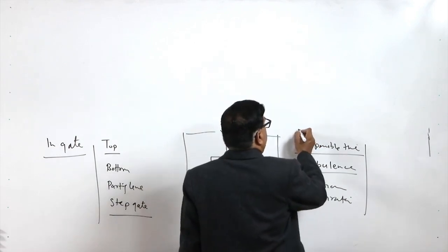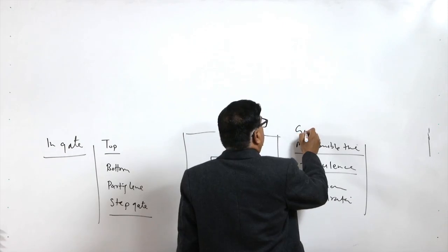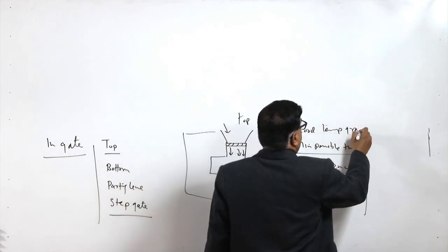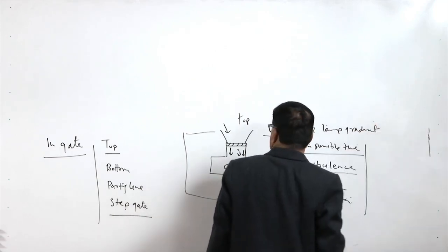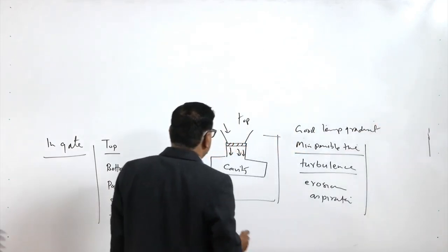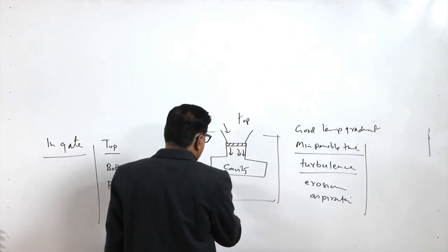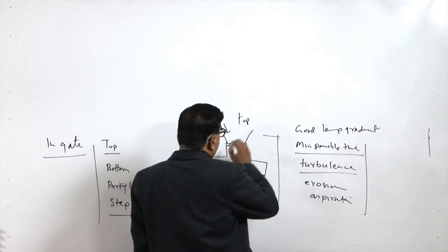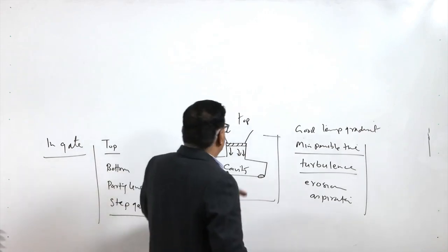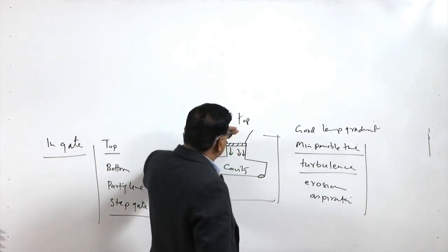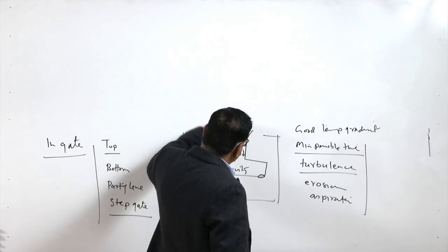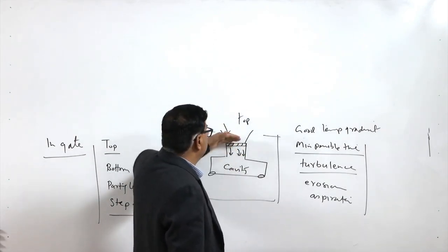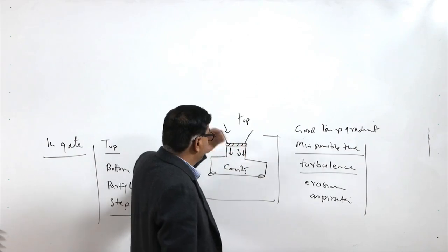Another favorable part is that a good temperature gradient is achieved, which means the molten metal is fed at the remotest possible zone first, and thereafter the molten metal fed last, when there is a top feeding, will be at the top.